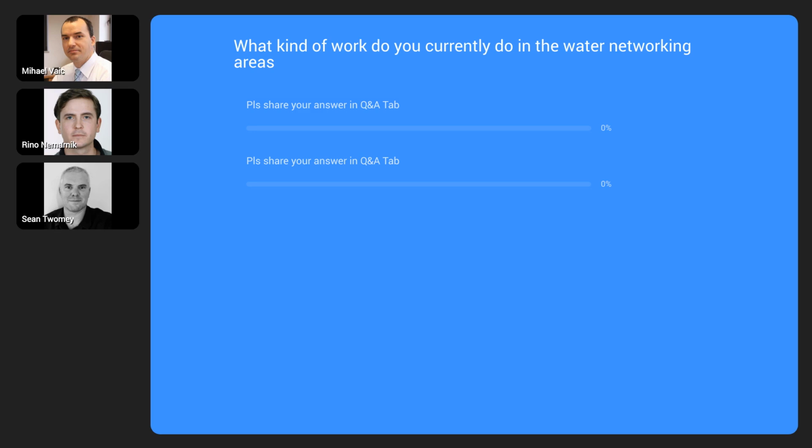So regarding all the equations, it is done like in EPANET, it is done with Softplan, and in the options dialog you have the possibility to choose between 3 different head loss formulas. So Hazen-Williams, Chezy-Manning, or Darcy-Weisbach. I think that would be the shortest answer. Yeah, that's a pretty complete set of offerings.